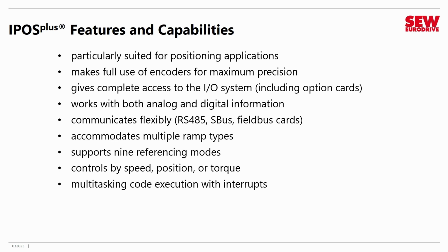You have something called multitasking code execution with interrupts. Now, if you know what that is, great, but if not, I'm just about to explain it, so don't worry about it. It's really a nifty little feature. There's also something called error handling and watchdogging. If you have a problem when the VFD is running, you don't necessarily want it just to die.